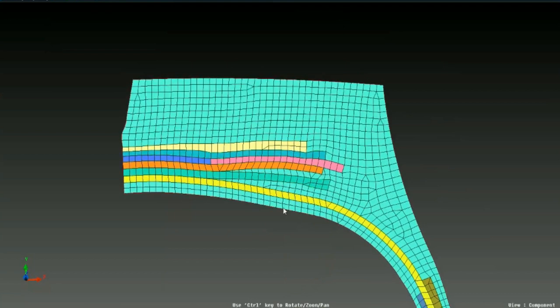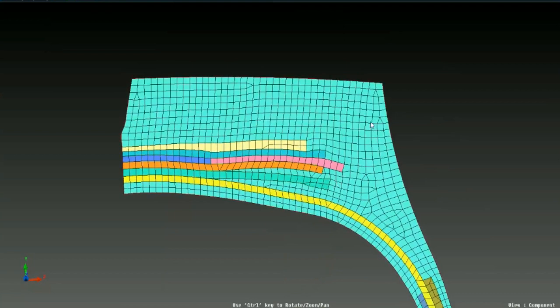Now by using our mesh quality control parameters, we can very nicely go ahead and do the mesh flow correction as per our requirement. We also have a few mesh editing tools, which are very useful while doing the quality correction, like shell remesh, mesh flow correction, split combine swap. In split combine swap, we have a swap option where you can just swap a tria with a quad, like you can see on the screen.